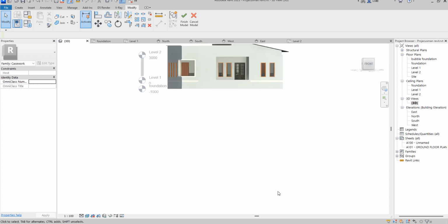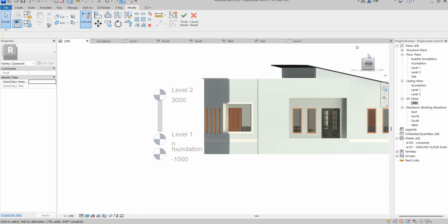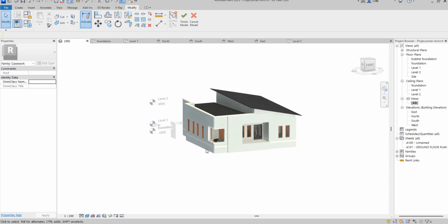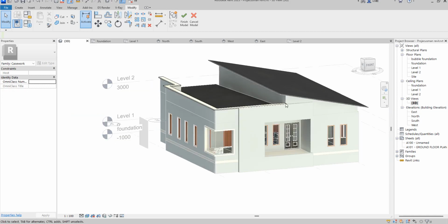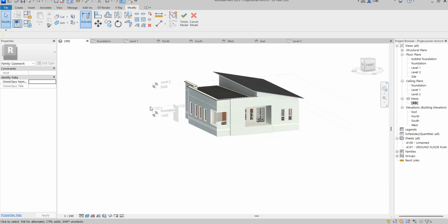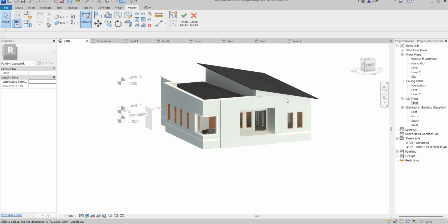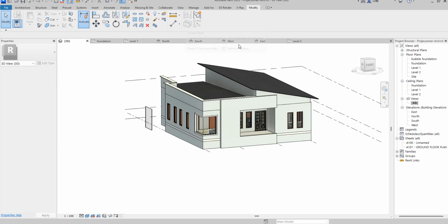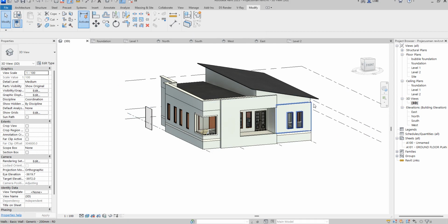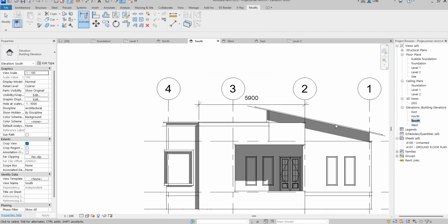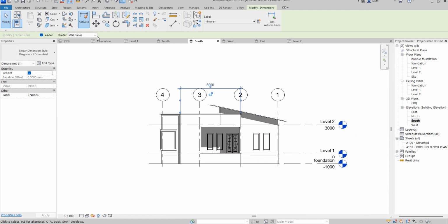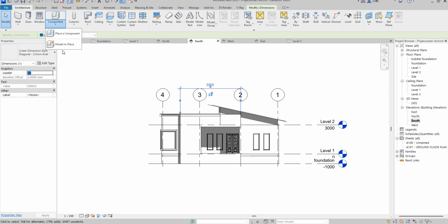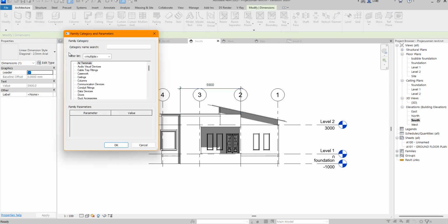So we are able to demonstrate the window aspect, and in the next design we are going to make the coloring and everything more perspective and unique. But before we go, let's quickly do the last part of what we have in this place. So I want to create a fascia for this roof. So I'm going to use the same method by clicking model in place, model.